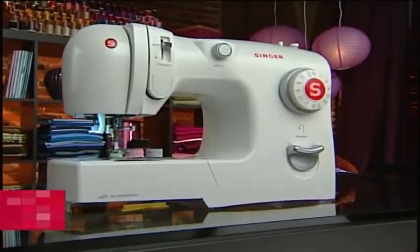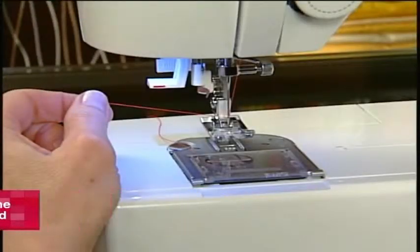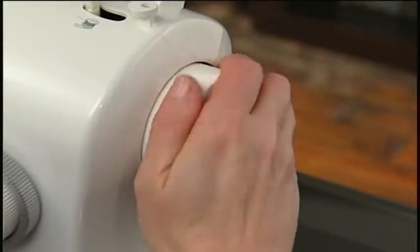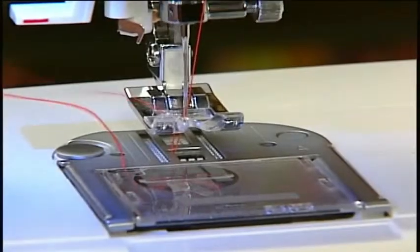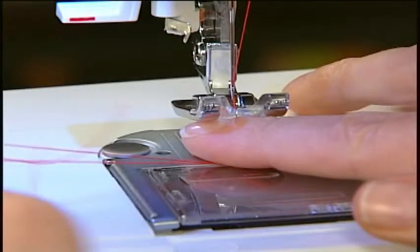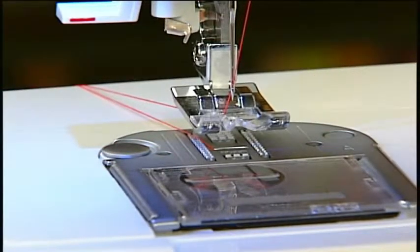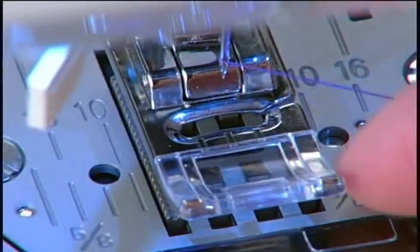Before you start sewing, you will need to raise the bobbin thread. To do this, hold the upper thread with your left hand. Turn the hand wheel toward you or counterclockwise, which will lower and then raise the needle. As you turn the hand wheel, lightly pull the needle thread. The bobbin thread will be drawn up through the hole in the stitch plate. Slip the threads into the groove on the foot, then place both threads under the foot toward the back. On some machines, the groove is in front of the foot, and on others, it is on the side.